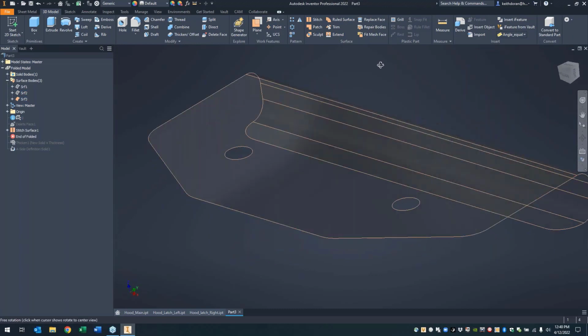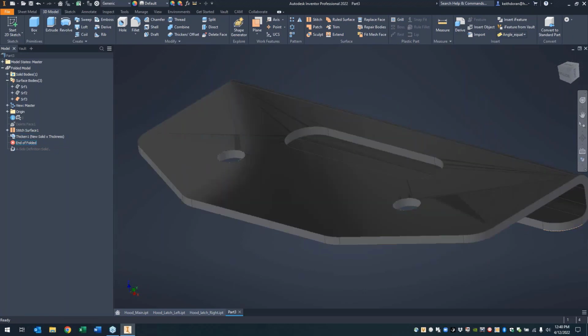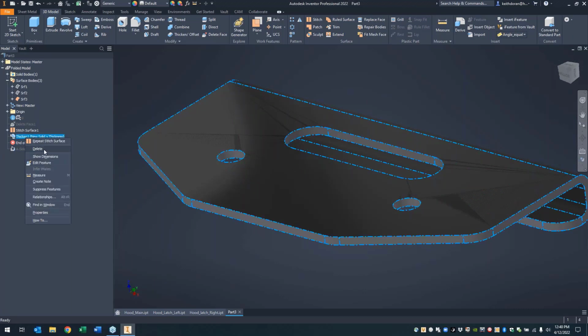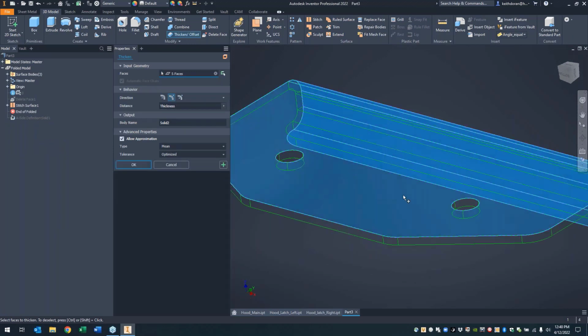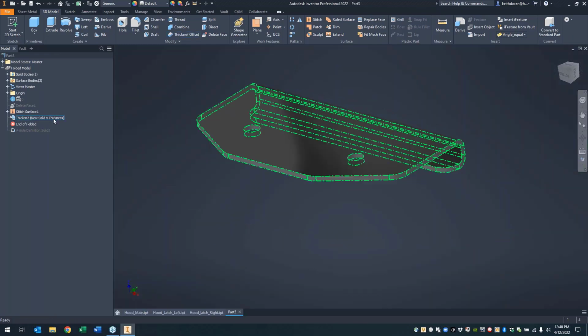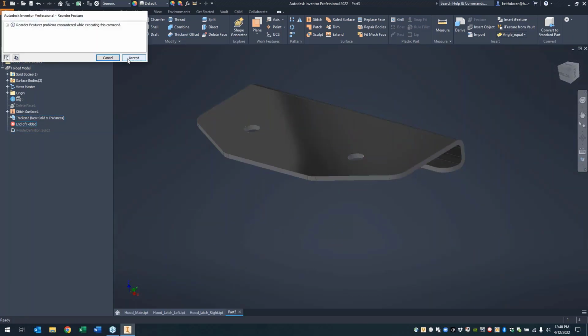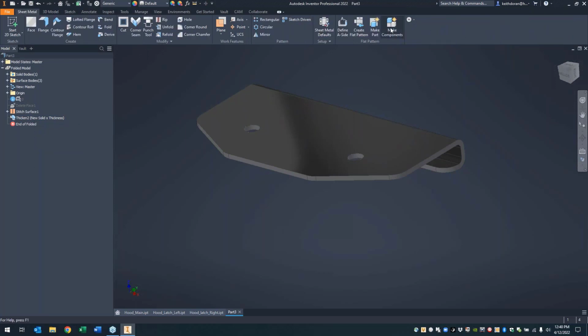Okay. Now that I've done that, I'll re-thicken the model. Let's edit the thicken, just delete that out and redo it. Face chain, the thickness downward. And now that I've done that, I'll turn the A side back on, which in this case is damaged, so I'll recreate it.